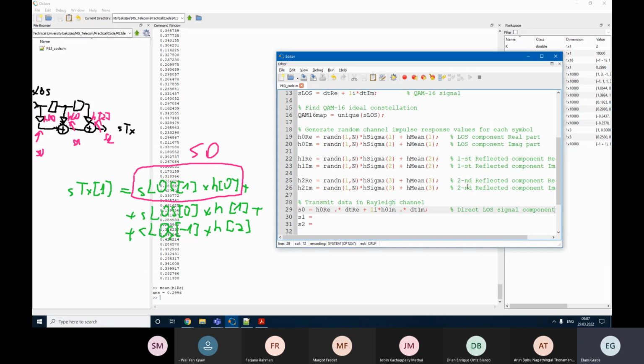So no problems. Later, however, starting from this, the idea is quite simple and straightforward. We need to change here for H1, but the problem is that we need to access the previous value. So we are going to introduce some zeros at the beginning, 1 0 here, and therefore take one less value, from n to n minus 1. This way we skip the last value of the signal just to have the same amount of symbols as in the first. We added an extra 0 at the beginning, so we have to skip the last symbol just to have the same length of the vector, right?